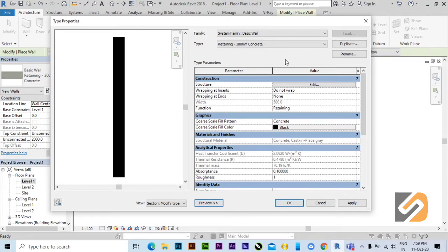How many families can you have? We can have as many families in a project as your computer performance or hardware specifications allow. The more families you have, the more load on your file, which means more specific hardware is required. The project will be heavier, with more toll on your system performance. So basically we can have more families, but always make duplicates of the families.